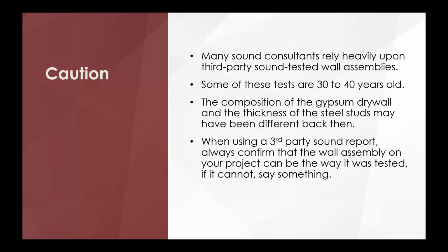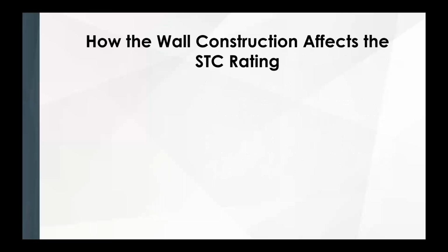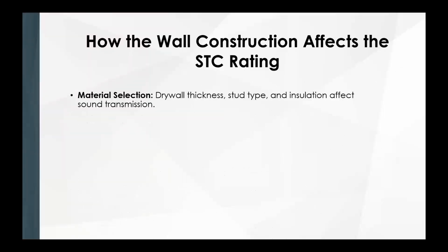You might also see that the drywall screws were the framing screws went through the top track. These are all things that you're not going to do in the field generally. So you want to make sure the way you're building it in the field is the same way that it was tested. Okay, so how could the wall construction affect the STC rating?